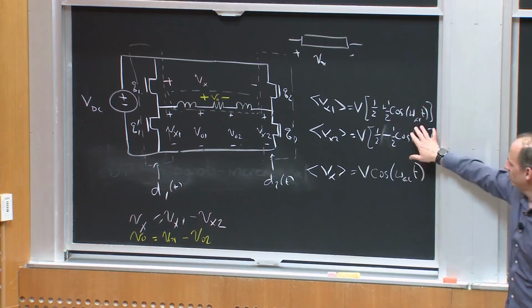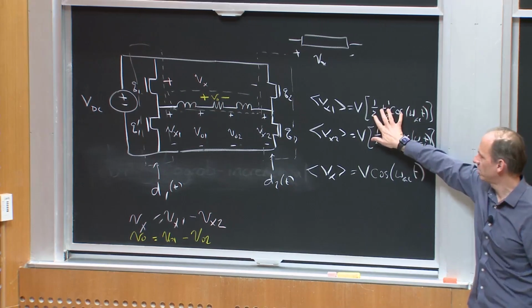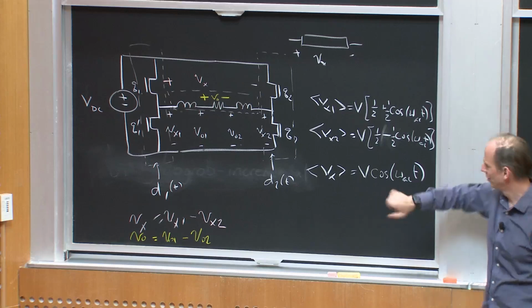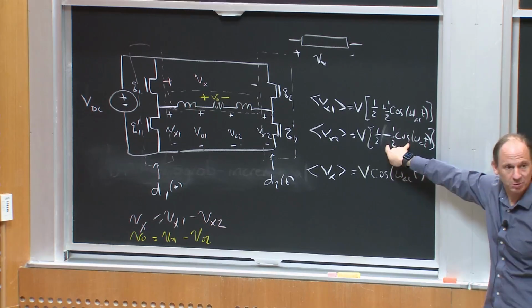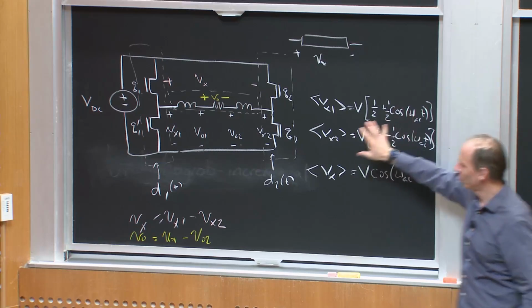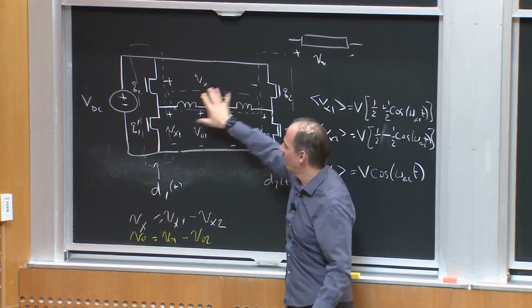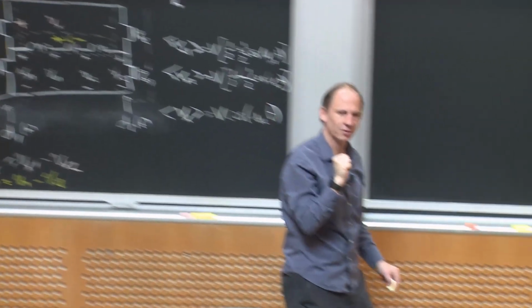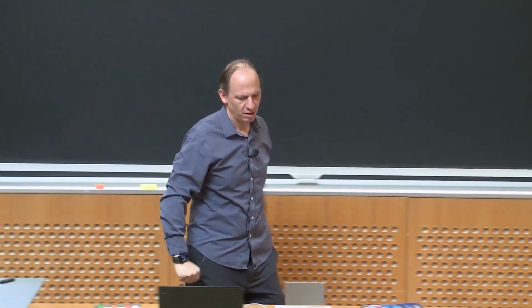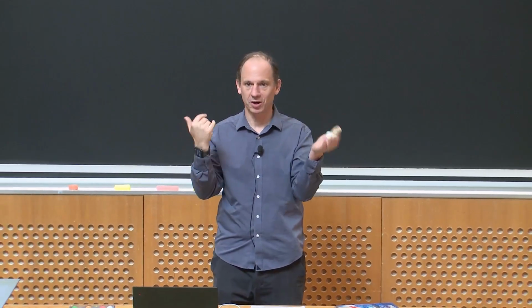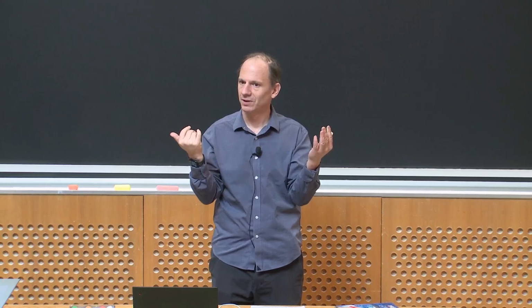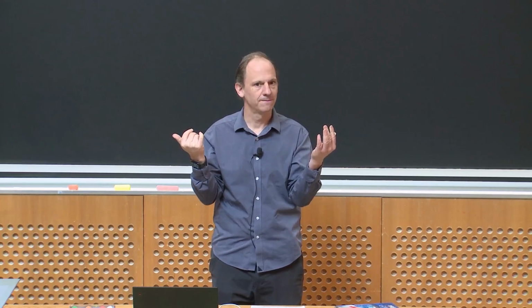So by synthesizing something with a DC component from the left buck converter and something with the same DC component but a complementary AC component from the right-hand buck converter, I generate an AC output voltage. Okay, so you could really think of a full bridge inverter as being 2 synchronous buck converters back to back. Okay, any questions about that?